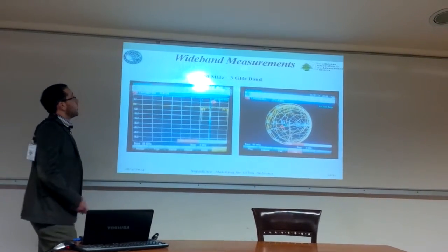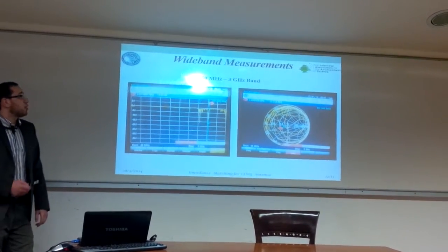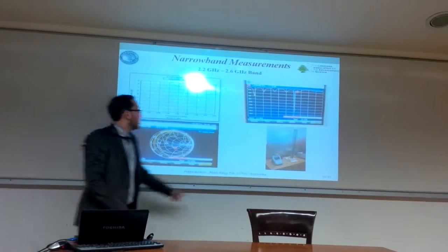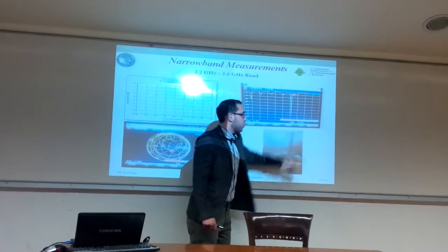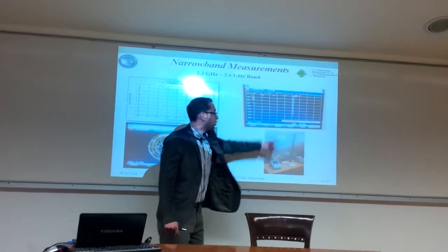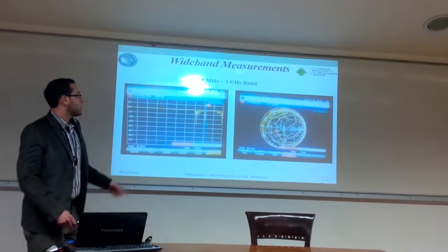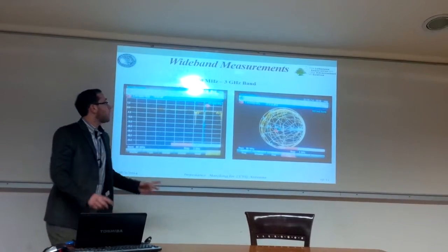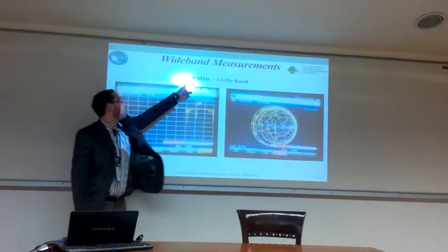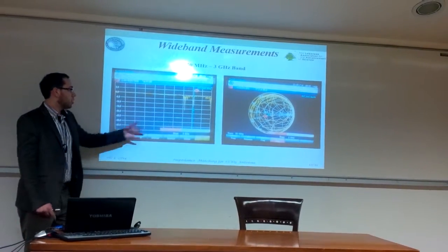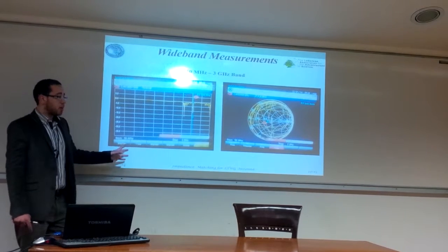Okay, now we did another second time measurement. Here the measurements were done between 2.2 and 2.6 gigahertz, and our study was at 2.4. The second study had a wider band, between 50 megahertz and 3 gigahertz. It is the whole band that is provided by the network analyzer.